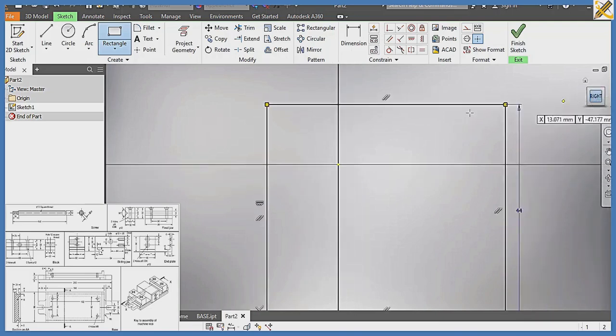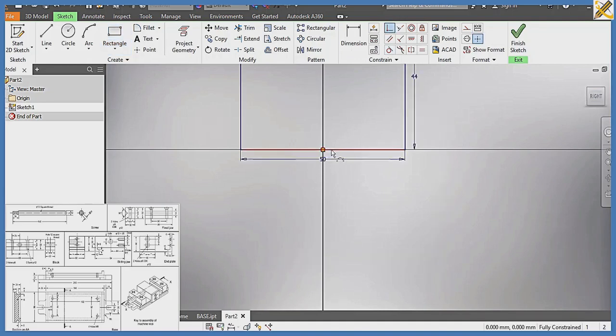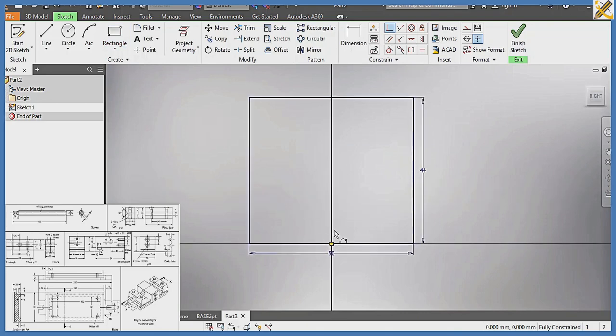All right, then pick my coincident constraint. So pick the midpoint, align it right here. I'm having this right about now, so I'm going to pick a line right here. So picking that line, standing right here, I'm going to draw across. Okay, then pick my dimension. The dimension of this line from here to here is mark of 6, enter. All right, so what is the next thing to do?